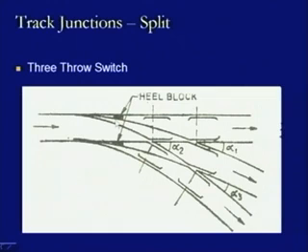So, this distance block will also come up to this location and will connect it like this, so that it remains in position. And there is an extra safety measure here, because we are providing one wing rail at this location, therefore, the check rail has to be provided at this location opposite to it. Whereas, because we are having 2 more crossings being provided here, they are just coming overlapping each other in the similar position because of the type of curvature which is being provided. So, here also we will be having a check rail being provided here and at this location.